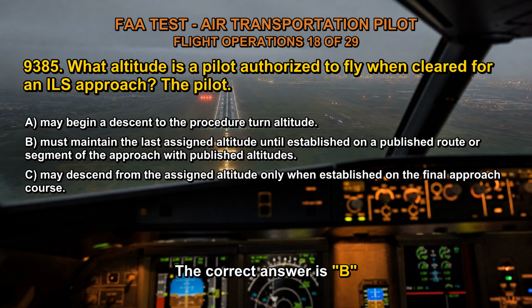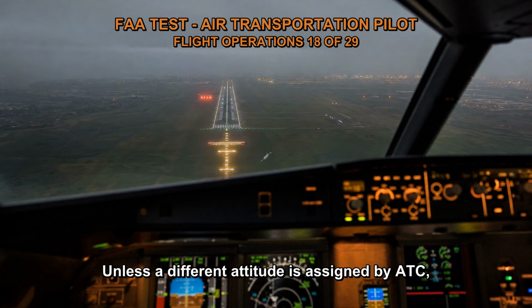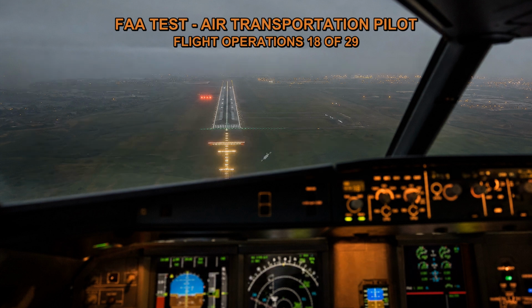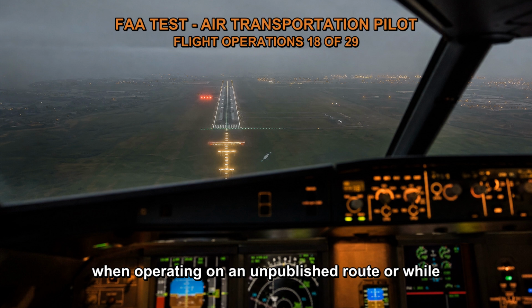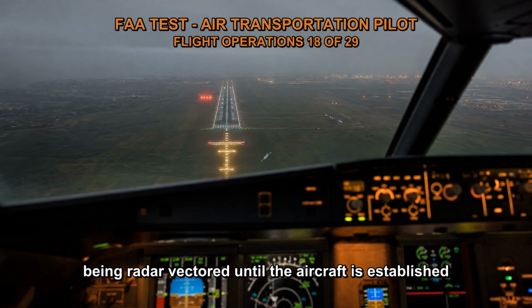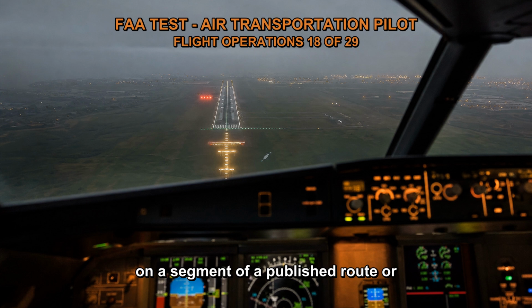The correct answer is B. Unless a different altitude is assigned by ATC, the pilot must maintain the last altitude assigned when operating on an unpublished route or while being radar vectored until the aircraft is established on a segment of a published route or instrument approach procedure.